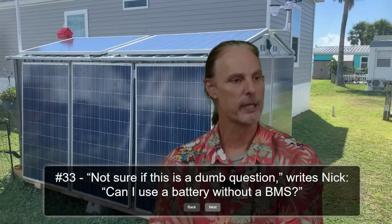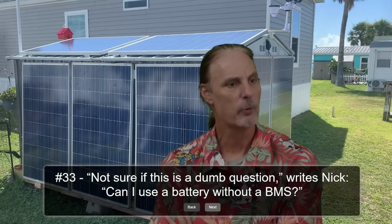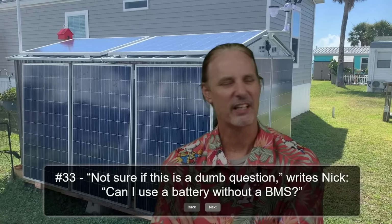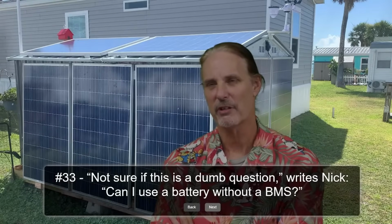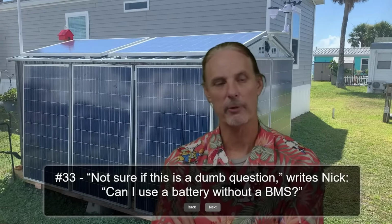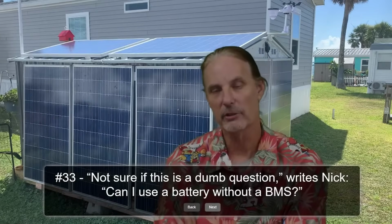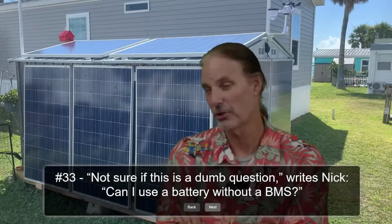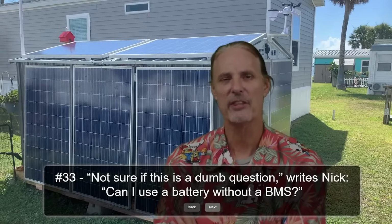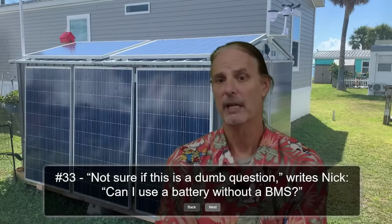Question number 33 is, not sure if this is a dumb question, writes Nick. Can I use a battery without a BMS? I don't know if I covered this before. It sounds familiar, but no, you cannot use a battery without a BMS unless it's not a lithium iron phosphate. I would not connect lithium iron phosphate without a BMS. Can you? Sure, yes, you can. But it's a bad idea. The BMS is there to protect the battery, to protect your investment, to protect against bad things from happening. Always.